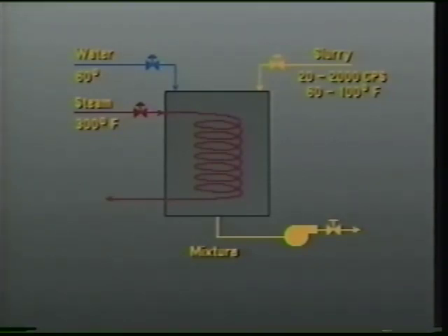In our example, the loads are as follows: water temperature, water flow rate, slurry temperature, slurry flow rate, slurry viscosity, steam temperature, steam flow rate, mixture demand, and ambient temperature. Now, each of these loads needs to be studied so that the parts of the process that each load affects can be isolated as a basis for developing a control plan. Once this is done, the plan can be visualized by adding appropriate control valves in the process lines where applicable.